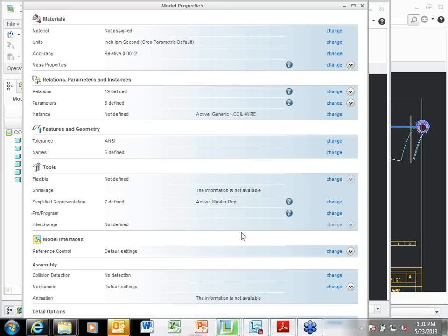A good example of that would be, let's say I have a tractor and I have engines, transmissions, bodies, hoods, three-point hitches, whatever the case may be, with all the functions on it. Each one of those groups becomes a function of a master. And that master is the subassembly, called engine relative or transmission relative, or whatever I'm working on.